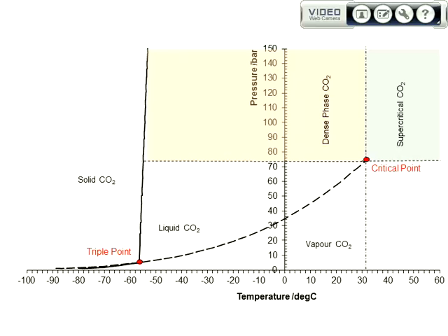If you can't operate in the dense phase, what is the maximum pressure you can operate in the gas phase? And remember, there's no point in saying, well, you can operate at a pressure like this, because it means as soon as you drop the temperature, you're going to convert from gas to liquid. Okay. Right, let's just have a quick look at the TD1.